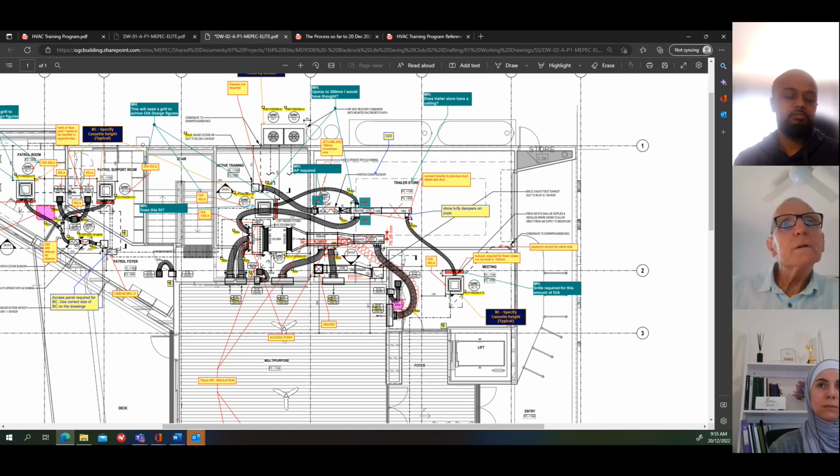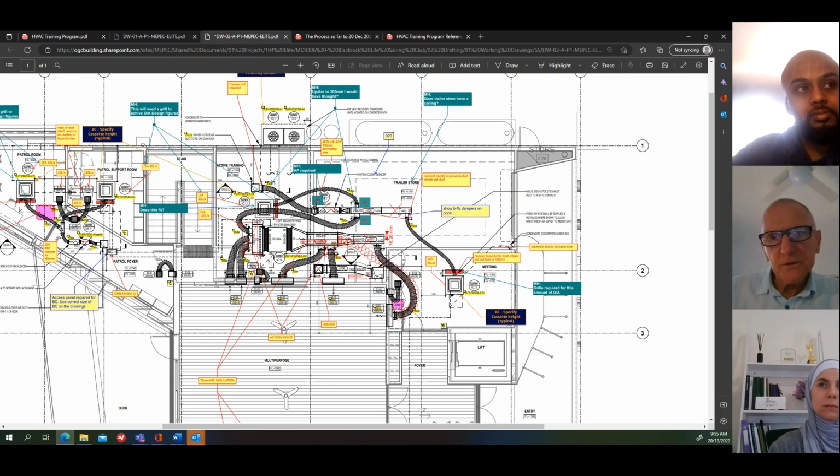Over here, what have we got here? There's a fan, a ventilation system, small one here. So this is extracting air from this outlet here through a flex. Now, that last piece has been crossed off. Actually, Jalen, I think I talked to you about this job, didn't I? In Melbourne. Yeah, that's right. We said we didn't really need that last piece of duct because you can have 6 meters of flex. So we said we can put that onto that duct and take that piece out.